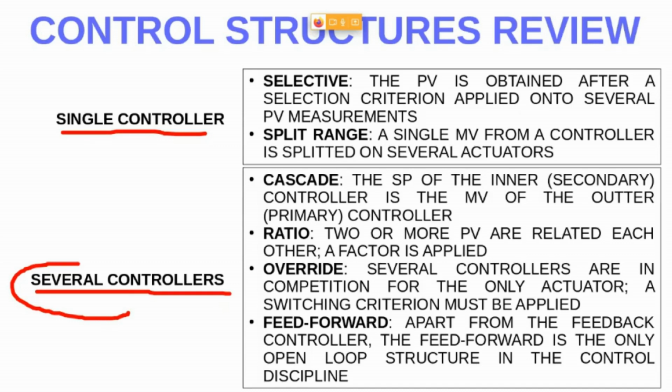If you use, for example, 3 transmitters, you can assume that one out of these 3 transmitters can fail, and the system will keep on working. Why? Just because this transmitter that fails is the single one that gives you a wrong measurement, right? Because the other 2 offer you similar measurements. So it's easy to know which sensor is failing. We're going to see an example afterwards.